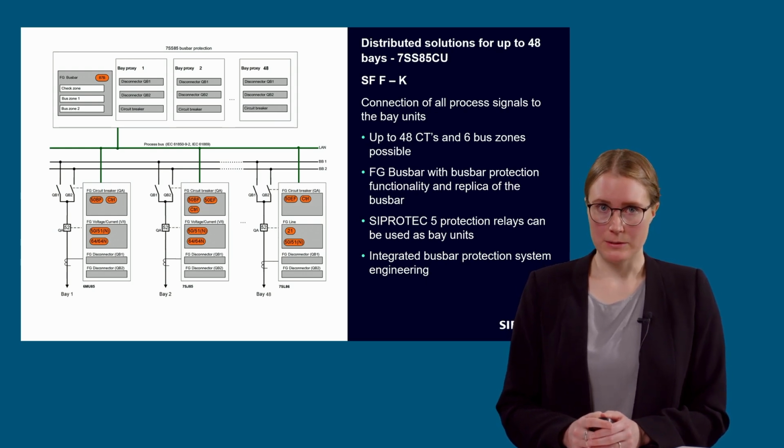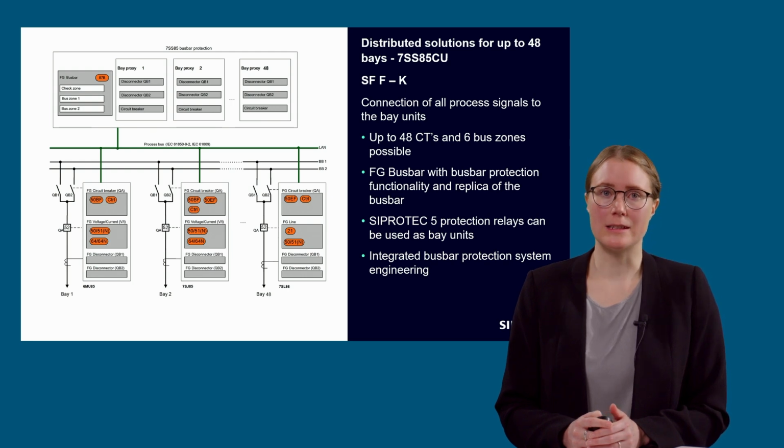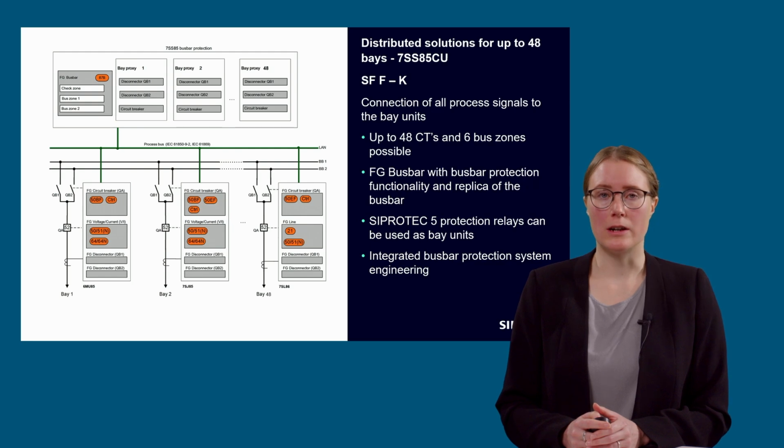The communication between the bay units and the central units is also based on IEC 61850. In the IEC 61850 system configurator, the assignment of the physical measuring points of the merging units to the central units in the sampled measured value view must be done. For this purpose, a script is provided which automatically performs the assignment according to the specifications from the single line diagram. The engineering effort is therefore significantly lower than with the IEC 61850 compliance solution.